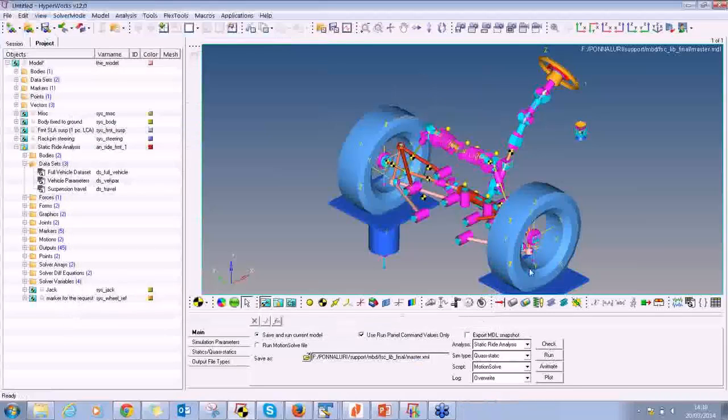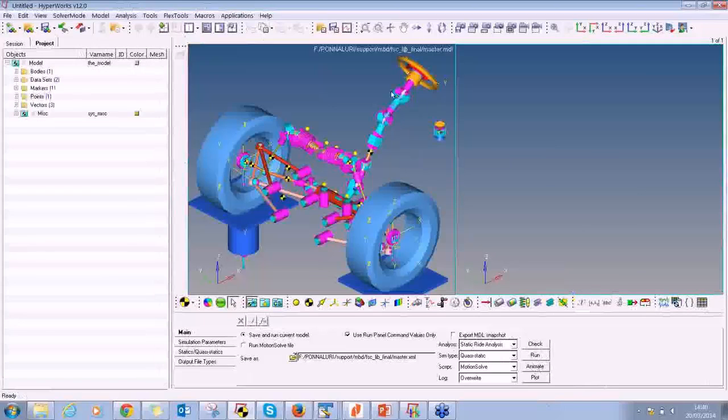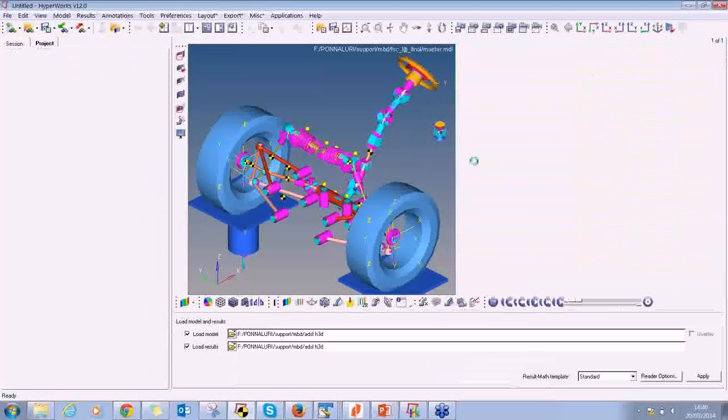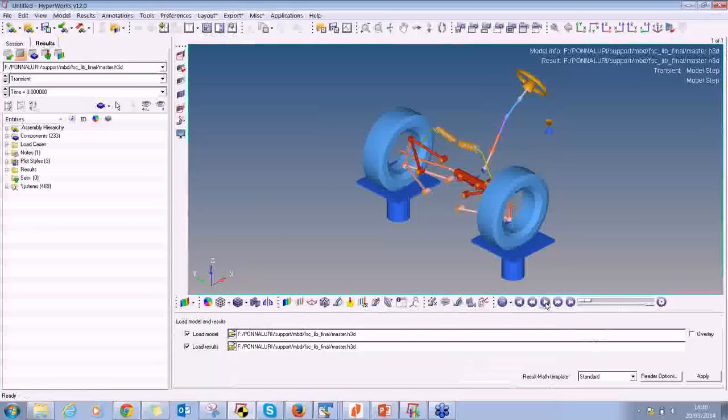so the analysis is complete, and what you are looking at right now, for new users of HyperWorks, is this environment called the HyperWorks Desktop, and it has multiple clients in the same environment. So you can also access the post-processing clients in the same environment as my Motion View preprocessor client. So if I click on Animate, I can get another window with HyperView loaded in it, and I can expand it like this and show you the animation.